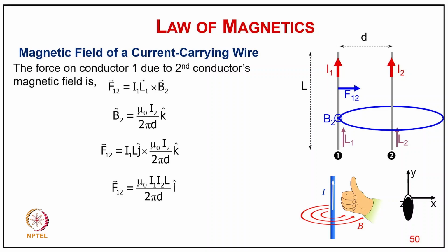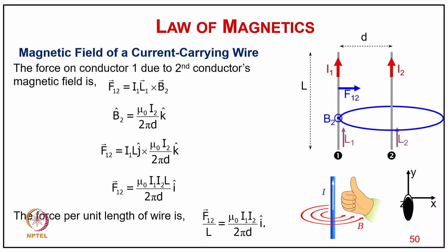So this is the force when two parallel current carrying conductors are there, and it becomes very relevant in many cases. Under normal conditions the force may not be very high, but when there is a very large excessive current because of some fault or some operating condition, like in a very large generator, say a turbo generator, if there is a short circuit, then very large forces are produced, and to take care of that we have to put in the winding with proper strength.